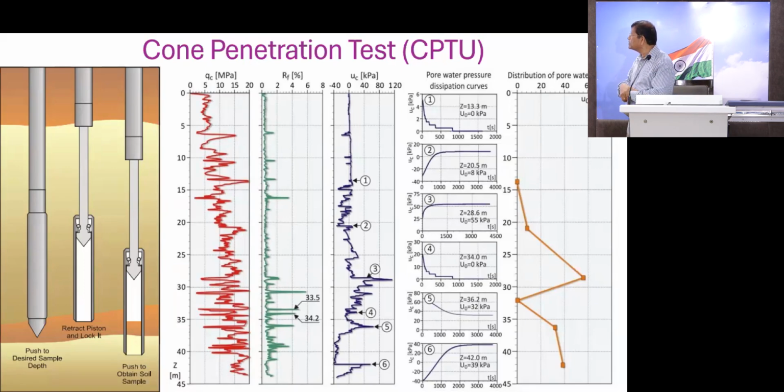Another important thing in the cone penetration test, which we cannot get from any auger testing or SPT testing, is the dynamic pore pressure and also the static pore pressure. You can get both. With dynamic pore pressure, we get the value while we are doing the test. The static pore pressure you cannot do continuously because it requires more time. Each test requires a minimum of 1 hour.